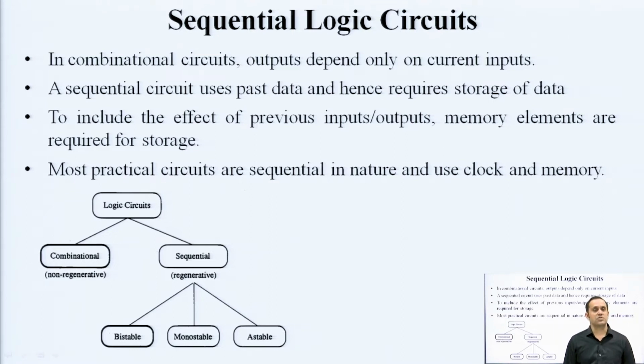This is known as the so called hierarchy in VLSI design. If I try to describe this hierarchy in the most general form, the lowest level, or the highest level of detail, is the material itself, which is being used to produce these semiconducting devices. You can start with silicon or silicon germanium alloys. That material level properties of silicon, say roughness, absorption and different material properties, are one level of hierarchy, which is at the lowest end and has the highest amount of detail.